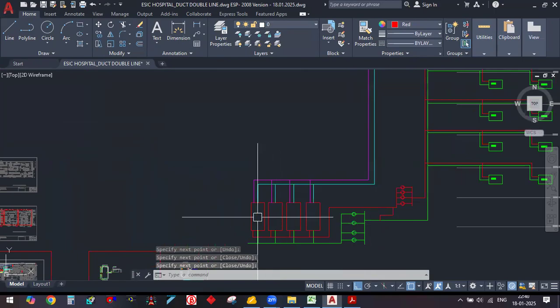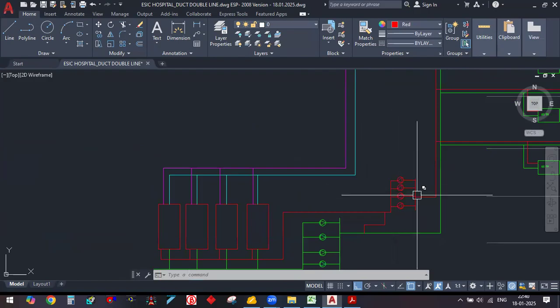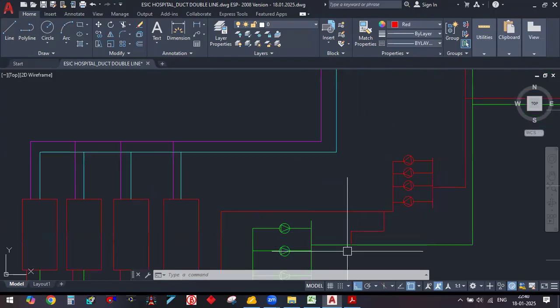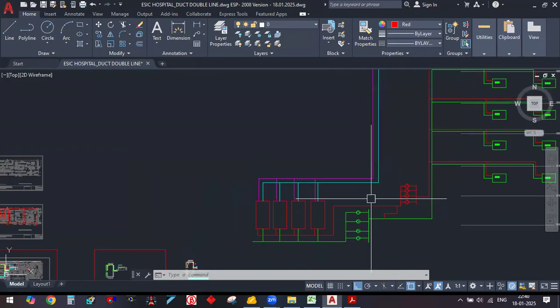See, what is the concept? Suppose the water is coming from here, chiller going to the building. So this is my distribution flow, right? And the water which is coming to the chiller is my production flow. Suppose due to any reason, the water which is coming back to the chiller is more, then it will be bypassed to this line. Suppose the water which is going here is less, so it will be bypassed to this line. So I think this is fine here.